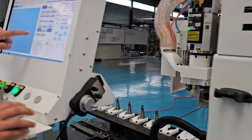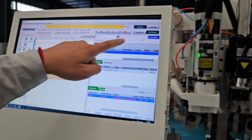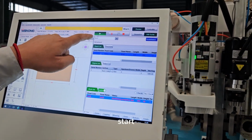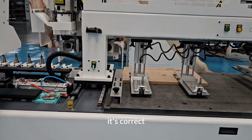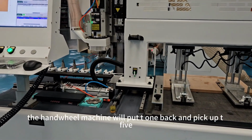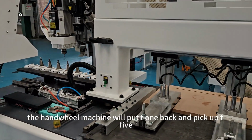Then we go back to process. Choose hand wheel, then press start. Now it's correct. Then we start rotate the hand wheel. Machine will put T1 back and pick up T5.